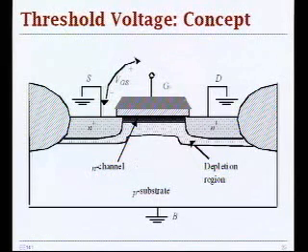And then when you keep increasing your gate to source voltage, you will soon reach some critical value that we call threshold voltage, where you basically invert the region of the channel. And instead of P material, you have basically N carriers under the channel. And then you can apply drain to source voltage to have these carriers move between drain and source, and you have a current conduction. So that's basically all you need to know at E141 level for device operation.